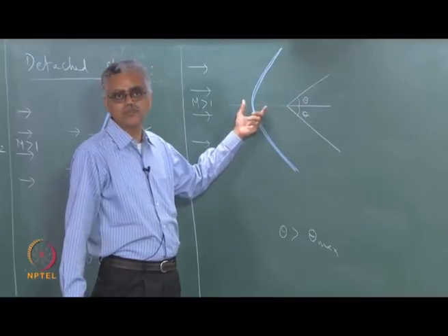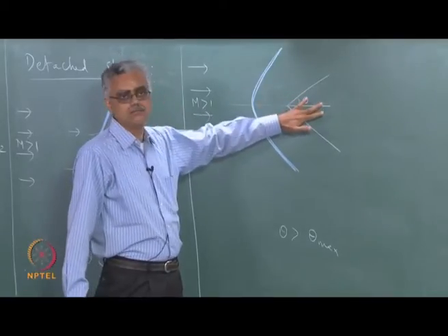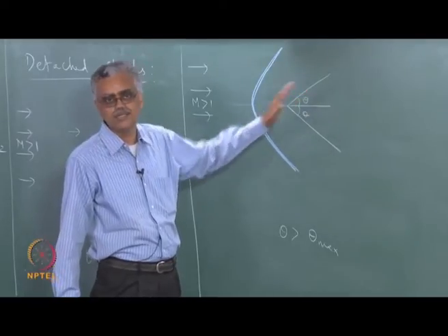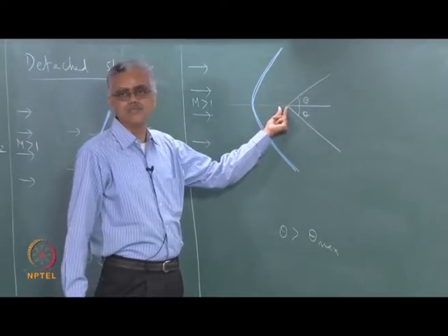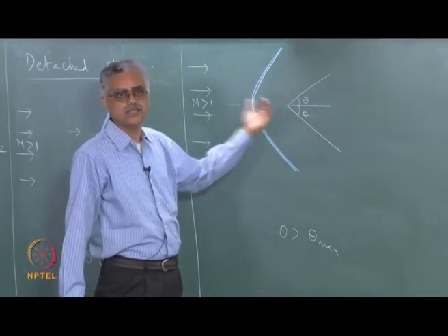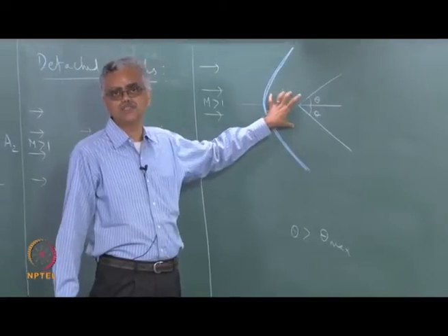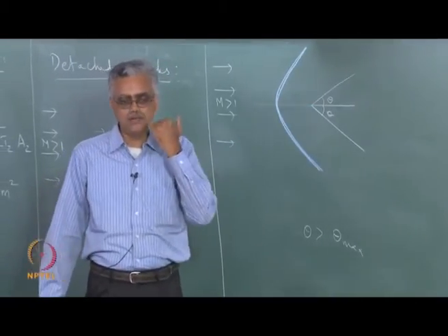body and the shock wave, depends upon the angle, how much more than theta max this is. If it is only slightly more than theta max, then the standoff distance will be very small. As it increases, the standoff distance also increases. This is extremely important in many applications, especially in re-entry flows.